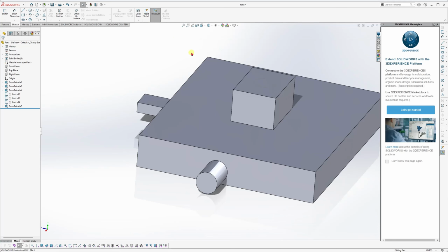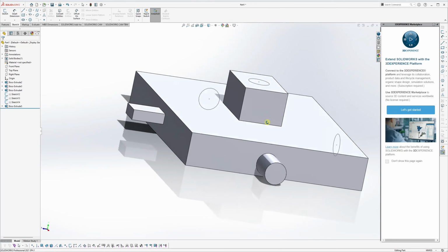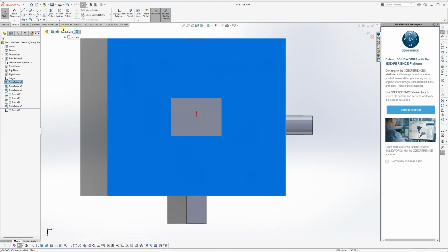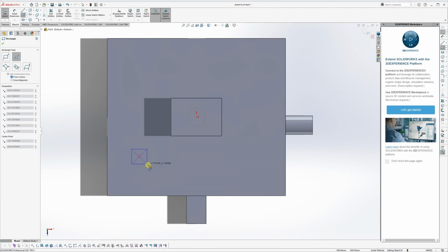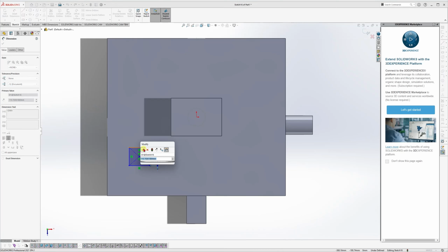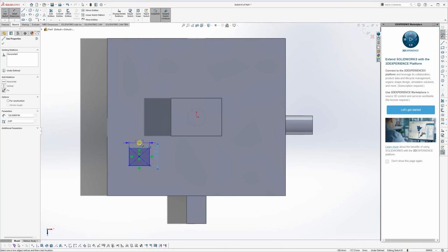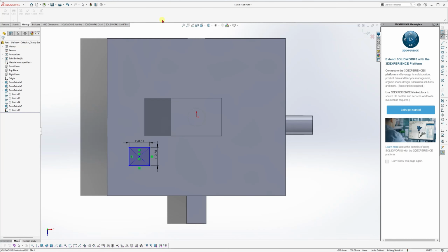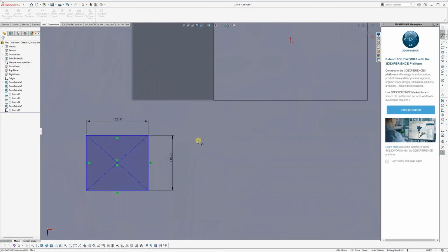Instant 2D is also useful if you want to change dimensions using a ruler. So, for example, I want to draw a rectangle over here. Then I have a dimension over here, and a dimension here also. Now if I turn on Instant 2D, or right now it's already on, go back to sketch.